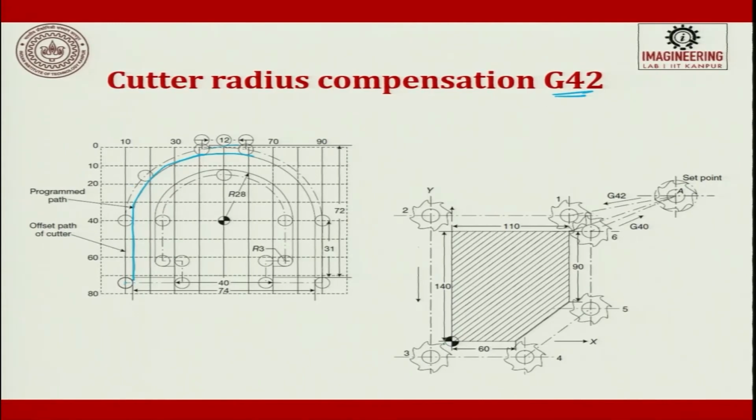When you look at it, this is the center, and here is your first point. The cutter comes in contact with the workpiece and starts cutting. From here the center is moved here, and this is your offset diameter. If it stops exactly here, it will try to cut inside the material. To avoid this, we offset by half of the diameter and move to the extreme out, so the tip must touch here. The center must be shifted.